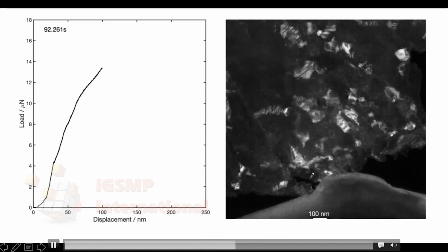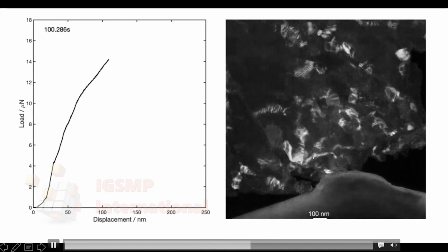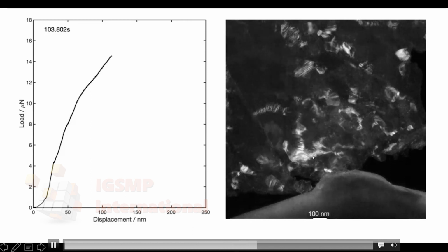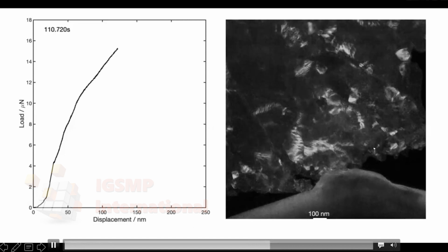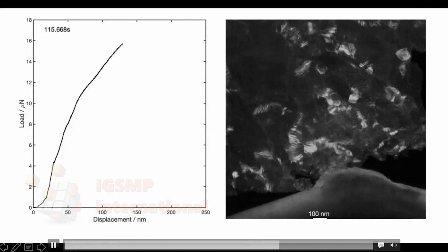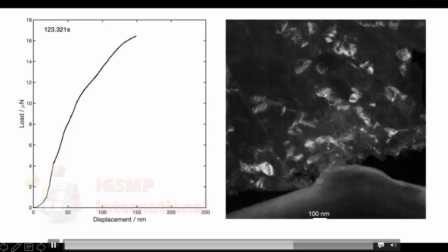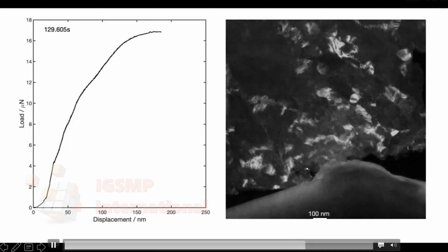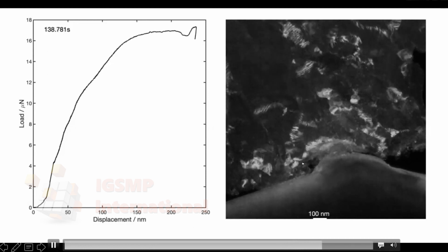And the interesting thing is that we can see the lining features which represent the dislocation activities there, and then the bright grains, which show that all those slip planes which we were targeting were adjacent or aligned to the vertical directions to the planes, and then they are actually linking together, forming a kind of pattern.